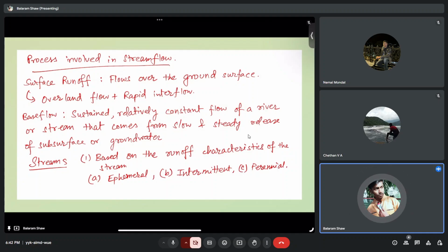The flow pattern is highly variable, and the rivers or the streams are mostly dry for extended periods. So what happens is that whenever a precipitation event happens, the stream or the channel gets the flow, and in the remaining time it is dry. So that is called an ephemeral river. Okay. Next, we have intermittent streams or intermittent rivers, right?